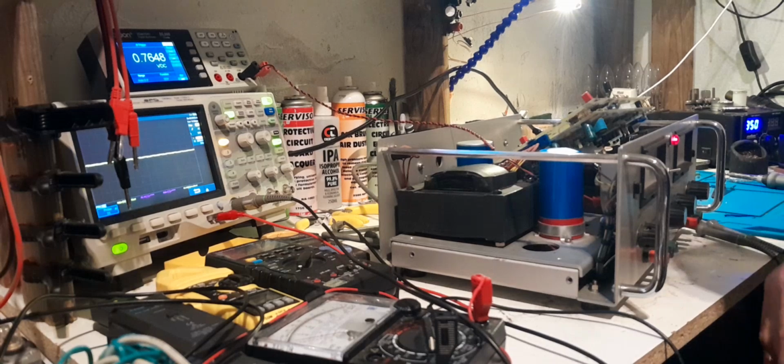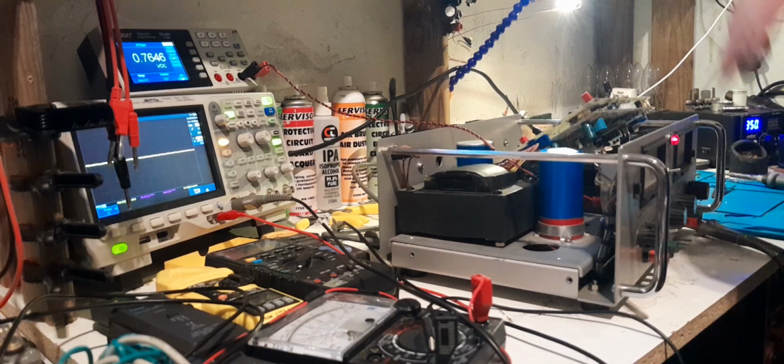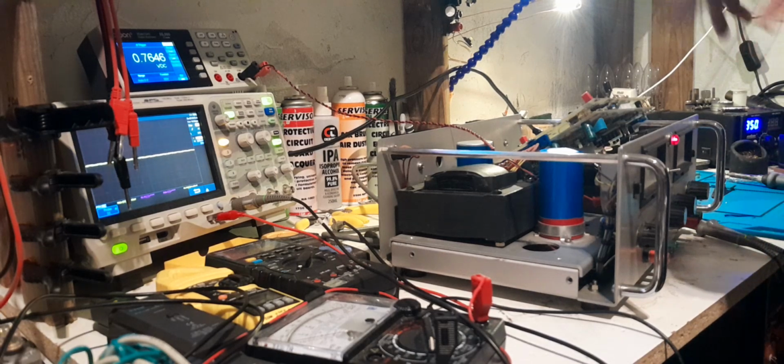Then I've got a reference, and that reference is adjustable, and then I've got another op amp that's looking across a little 1 ohm resistor that's in series with all the voltage feedback circuitry and tap changing circuitry and all that, so that I can look at what I'm calling leakage current to the output terminals, and then all that goes back to another op amp, or no, 2 op amps.